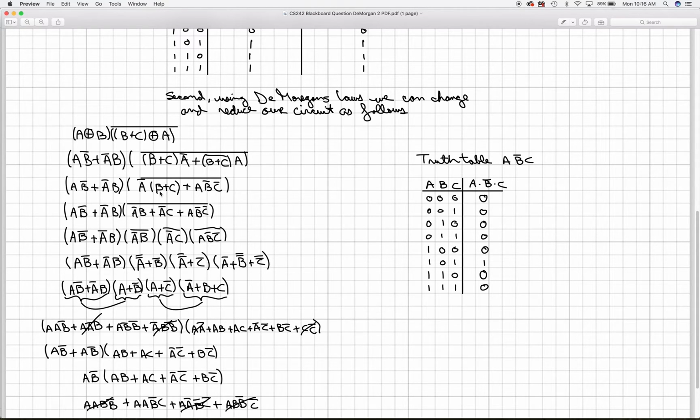For this part, I'm going to leave that overall NOT, that's all you can see written as the line at the top. And I'm going to AND these two, so that's going to be A NOT B. This is going to be A NOT C, and of course I ORed those two together. That is simply a rewriting of A B NOT C NOT. Okay, so now let's use DeMorgan's rule to break this apart.